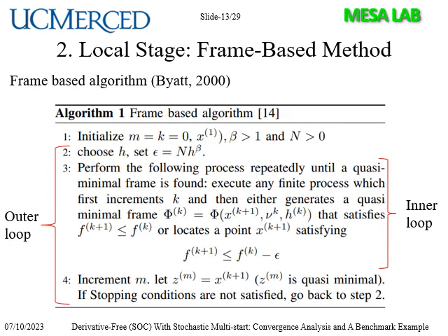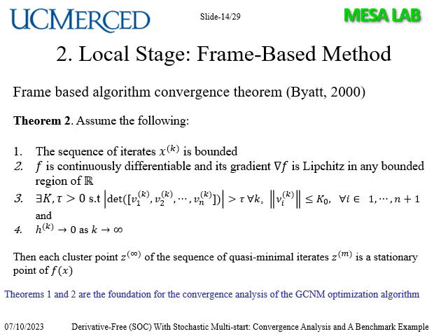So this frame-based algorithm is based on two conditions, that is the inner loop condition and the outer loop condition. Basically, the inner loop condition is the execution of the Nelder-Mead by itself, and in that sense we can make sure that if we are accounting for that deformation of the simplex, our self-optimizing controller, in this case our Nelder-Mead, will be achieving an optimal point.